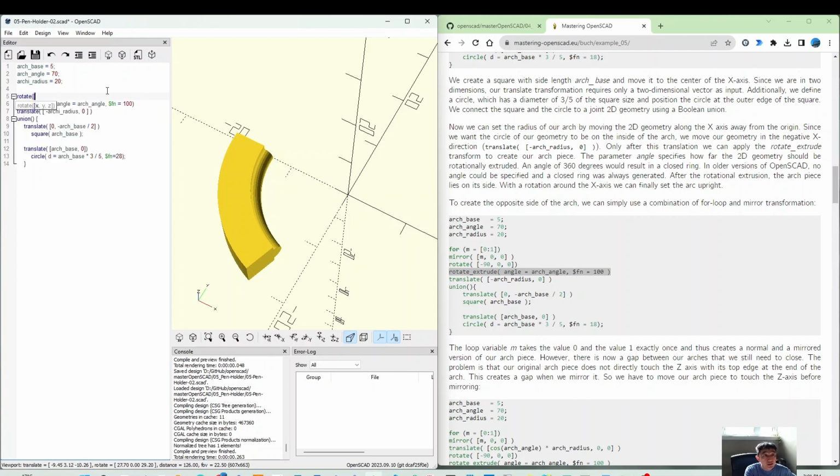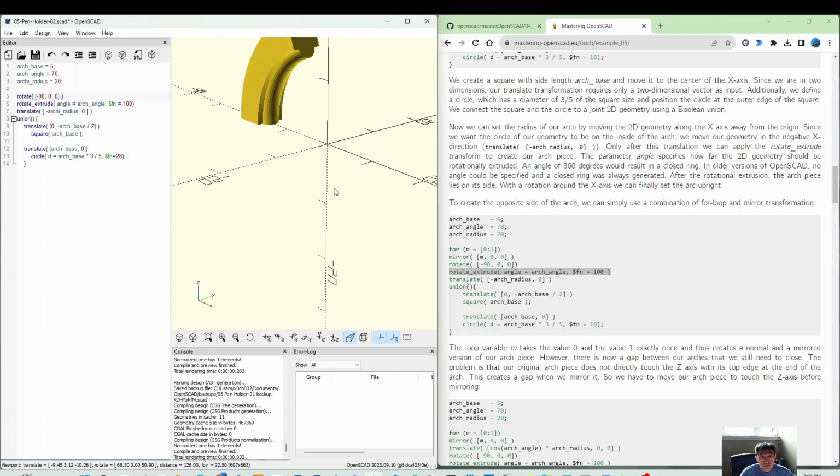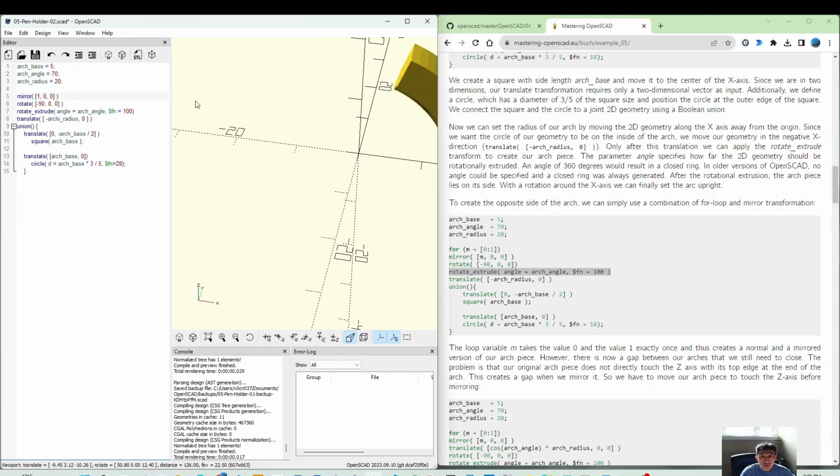Now it's already 3D. The shape, so you should use the 3D rotate, not the rotate in this 2D part. So what we did is we make this way. You can see we rotate based on X, and then we make our mirror. Let's see, if we do this on 0, 0, 0, then that's no change on mirror, so no change. But if we make that 1, that will change to here.